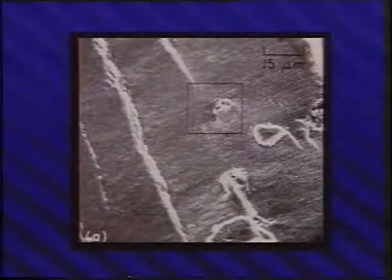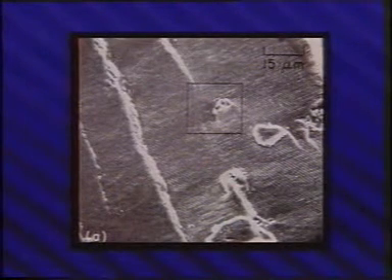Electron microscope examination of undamaged fatigue fracture surfaces in materials up to about HRC 50 frequently shows finely spaced parallel ridges or striations. These fatigue striations are oriented perpendicular to the microscopic direction of crack propagation. With uniform loading, the spacing generally increases as the striations progress from the origin of fatigue. Each striation is the result of a single cycle of stress, but every stress cycle does not necessarily produce a striation.